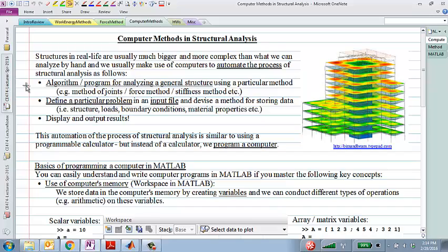You find the reactions and then you systematically go to each joint and solve for the numbers there. Right. So you basically find the reactions, and you can actually skip the external reactions also. You can directly go and draw the free body diagram of each one of those joints. If there are 10 joints in your truss, you draw 10 free body diagrams. You get 2 equations of equilibrium from each one of those joints.